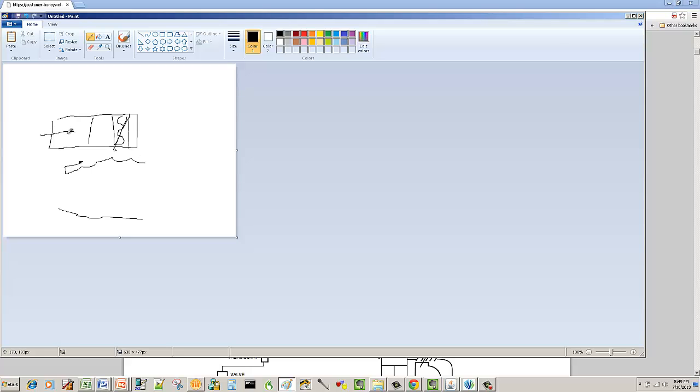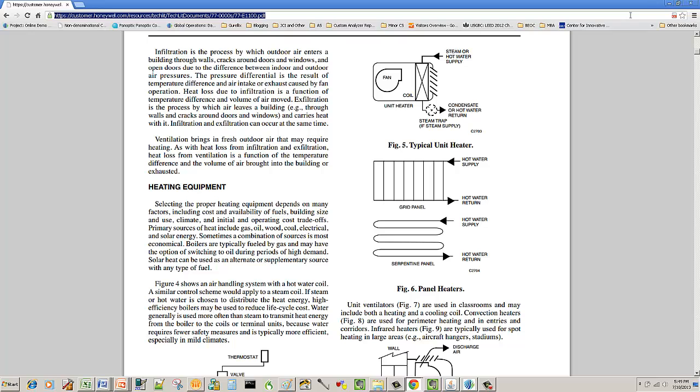Now when you slow down the air, naturally you're going to adjust your exhaust, so you have the same air changes, but that slower air is going to get a better heat exchange because you're introducing BTUs versus taking BTUs out. I know, wonderful picture. It doesn't look anything like a VAV box, but that's okay. You're not here for my art. You're here to learn about HVAC.